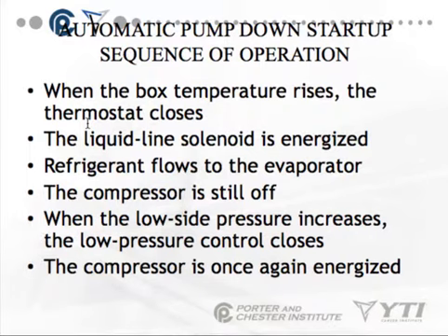When the box temperature rises, the thermostat closes, the liquid line solenoid is energized, and refrigerant flows to the evaporator. The compressor is off until the low side pressure increases to the cut-in point and energizes the compressor.